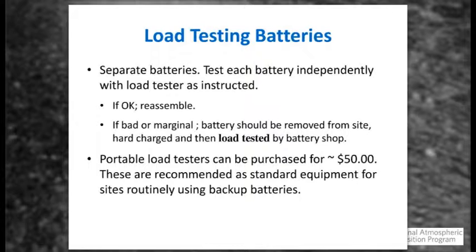As was noted there, if any battery is bad, one thing you can do is take it back to your office or your shop and use a battery charger to see if it will take a charge. Maybe sometimes it's just not getting enough charge in the field. We do recommend load testing, because if it fails load testing even after manual charging on line power, it's just going to weaken your overall system. It's not really contributing anything if it's failing load testing. There's a note there: portable load testers can be bought for about $50. It is good to have.